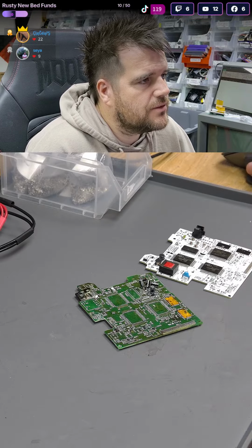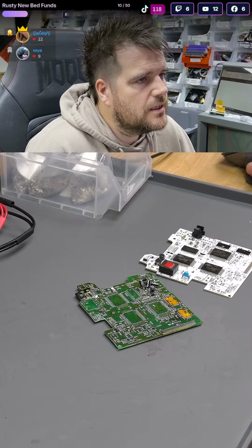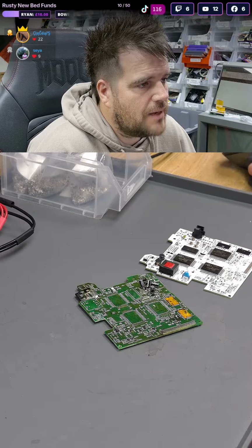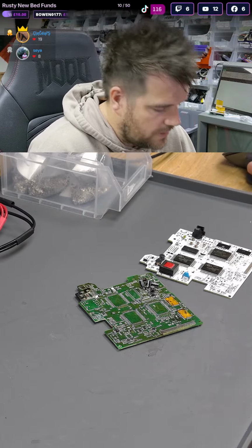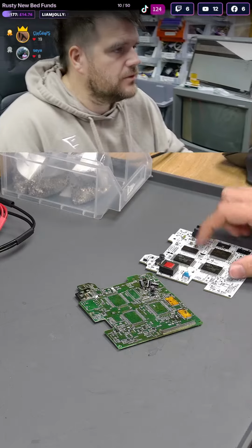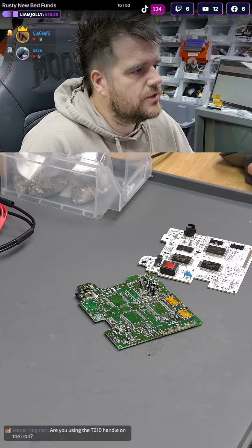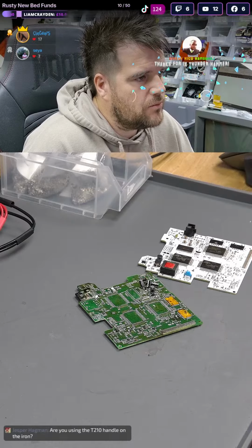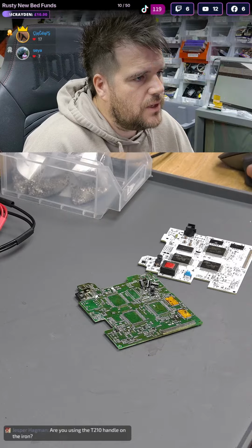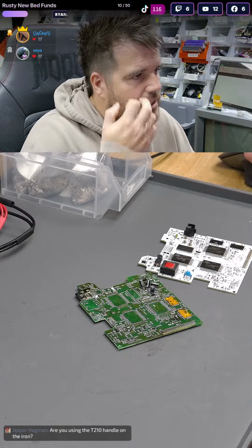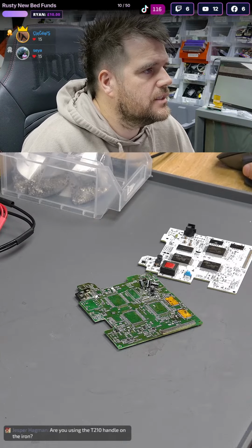Alright, so I'm just going to scan through the desktop PC Engine schematic, looking for some caps that are very low. I don't know where this is at. Oh, it's going to be the crystal. It's right by the crystal. So if I look at the crystal circuit on the PC Engine, although that's quite high for a crystal capacitor, it's almost likely going to be related to that crystal. So this is going to be pretty important to get right.